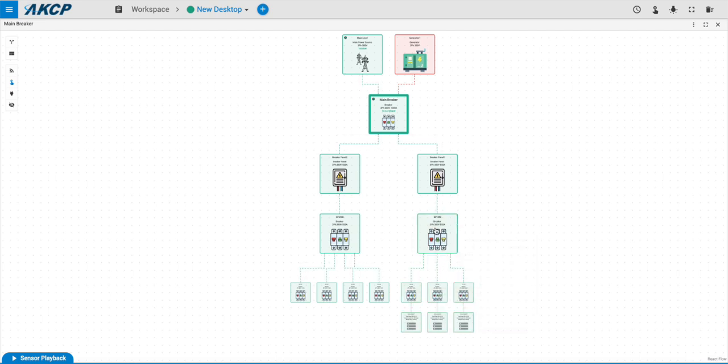Now, if you connect these up to intelligent circuit breakers that have, say, a dry contact input on them, then you can automate this. You'll be able to see in the live view which of these breakers are active and not active. So if you've got a power outage in a part of your data center facility, you'll be able to go to this powertrain, and in that live view, you'll be able to see that this area is off, and probably because this breaker or the problem starts at this particular panel. So that's the first place for you to go and start tracing the problem.